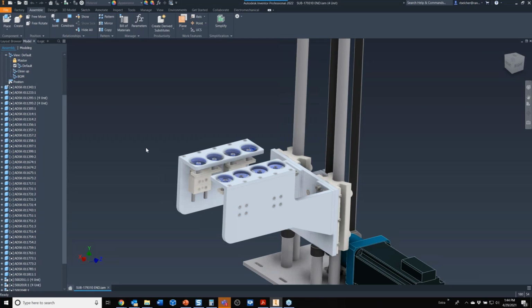If you go away from the event today with one big takeaway about model states, if you can get it in your mind that they replace levels of detail, that's great. But understand that they also duplicate the functionality of iAssemblies and iParts, but with a single document workflow. Take that message away with you, and on top of that there are so many more opportunities available to us with model states now.